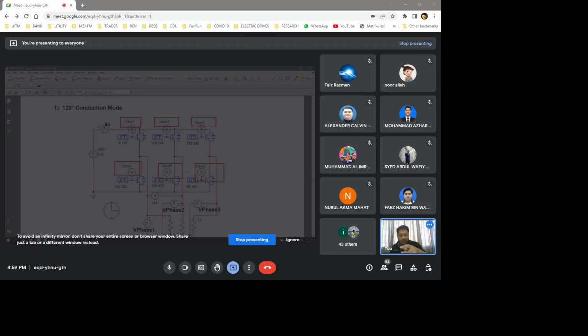If you label in the wrong arrangement, when you prepare the control signals, it will not match, and you may not have the correct output voltage waveform. So you must have S1, S3, S5, S2, S4, S6, and then you generate them.